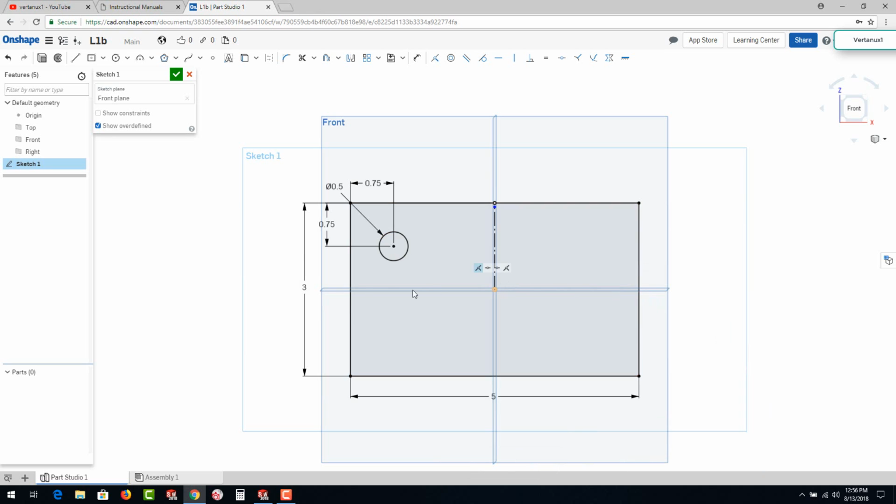All right, so let me continue on with drawing another line. Click here, drag it out, connect, hit escape on your keyboard, and now right click on the line and set it to construction. So now we have center lines. Those are the primary ingredient required in order to mirror.